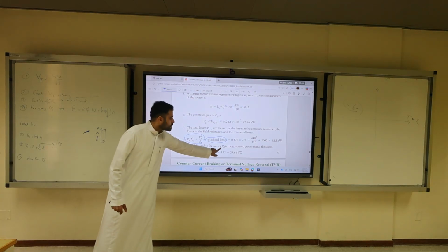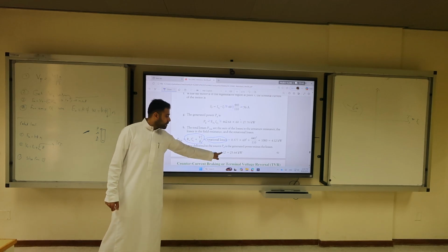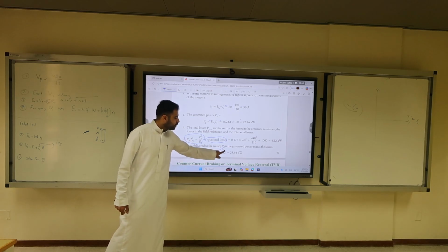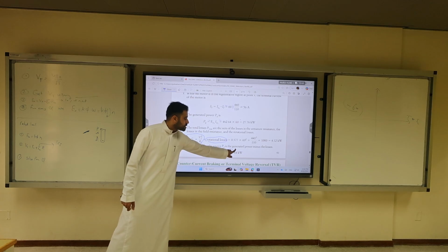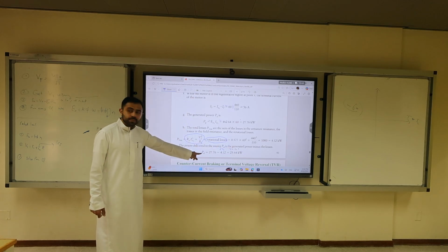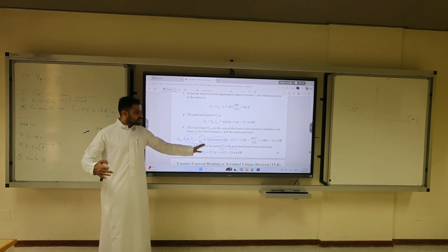It should be minus only the electrical losses. Do not include the mechanical losses here. So he leans more toward minus 3.12, which is 24.64 kilowatts, because this is developed before the rotational losses. So this is a correction.